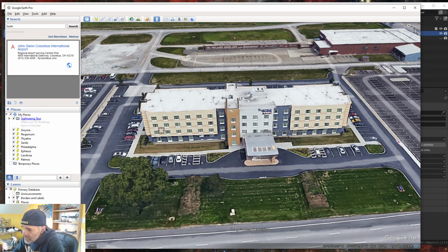All right, so anyway, we're going to cut out this series of windows using some loop cuts. So let's get to work. This dimension here I measured when I was laying out my building to be 86 feet. And I have 6 columns of windows. And those windows are 6 feet across. All right, so we need to start laying out our loop cuts for these windows.